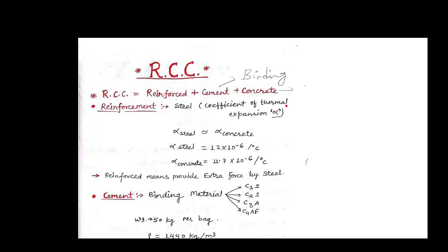Here reinforced means to provide extra force by steel. As you know that concrete is much strong in compression, but it is weak in tension, or you can call it as flexure. So we provide steel as a reinforcement to provide the structure extra strength in flexure.